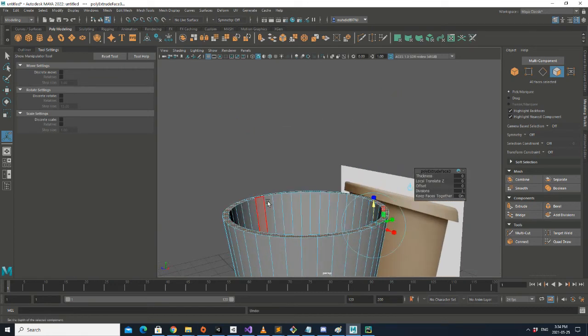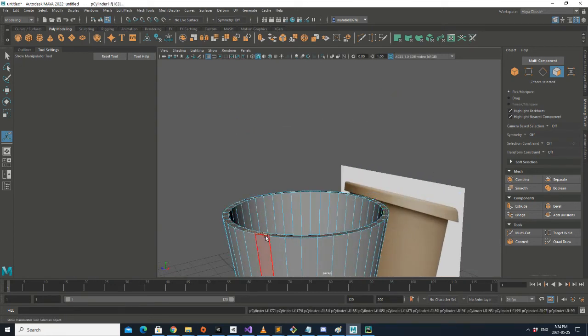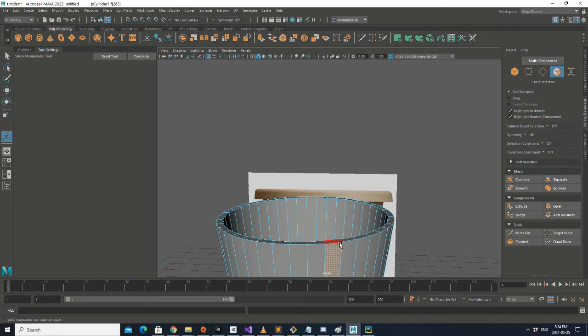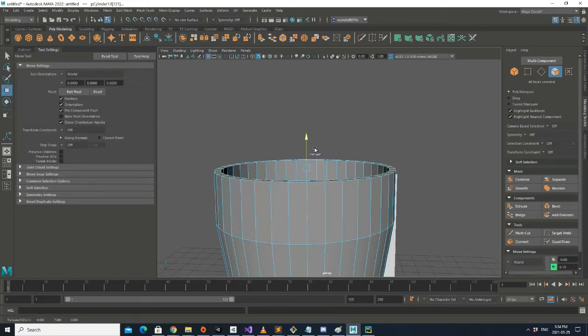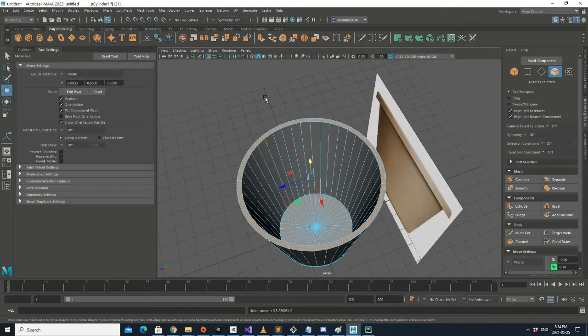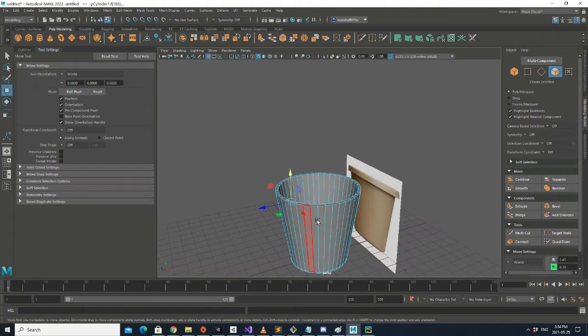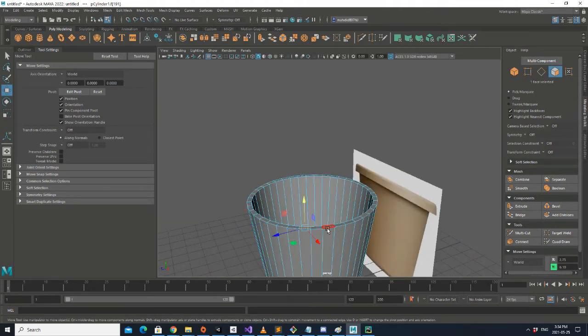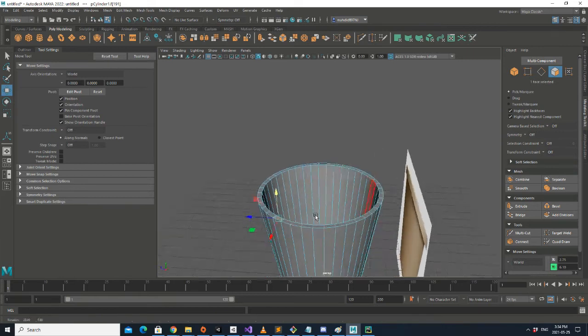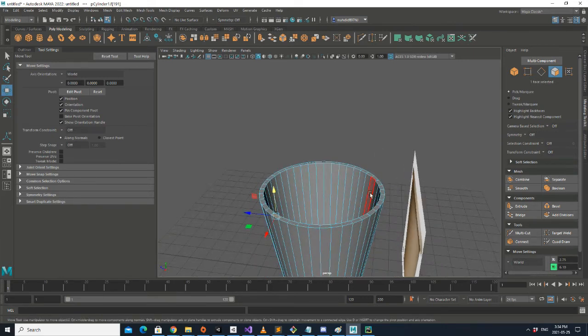Maybe a shortcut is to just use shift. So selecting these faces, then going to move and holding shift and moving them upward is also okay. Again, select the faces instead of the edges and then extrude the faces. That's important because if you just select the edges and extrude them, then your model thickness would be 0. It's just a very thin plate around your model.